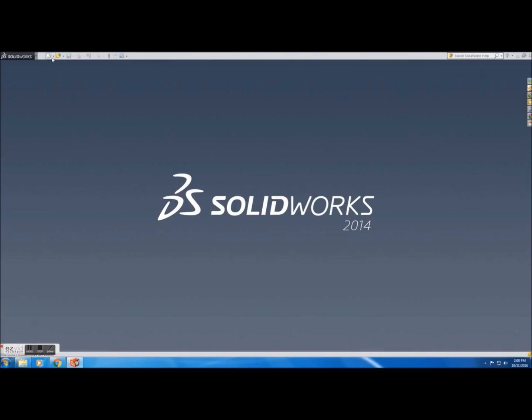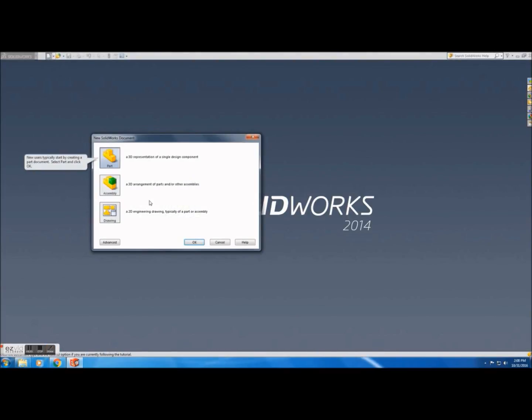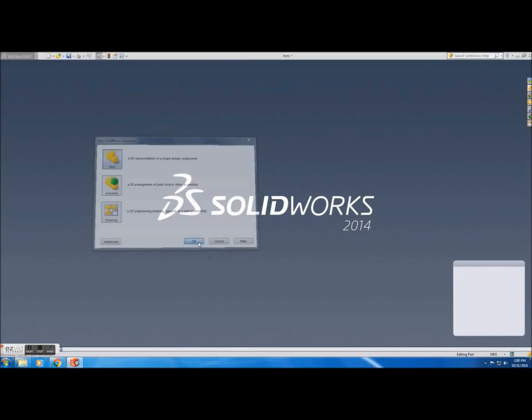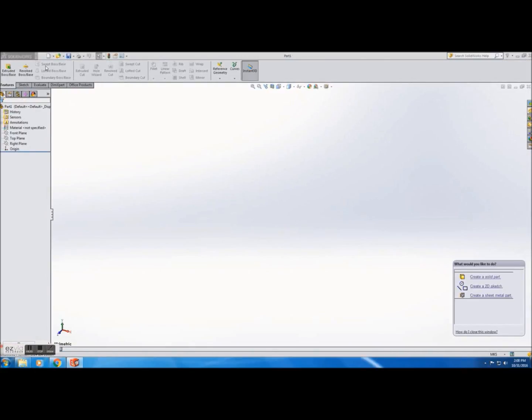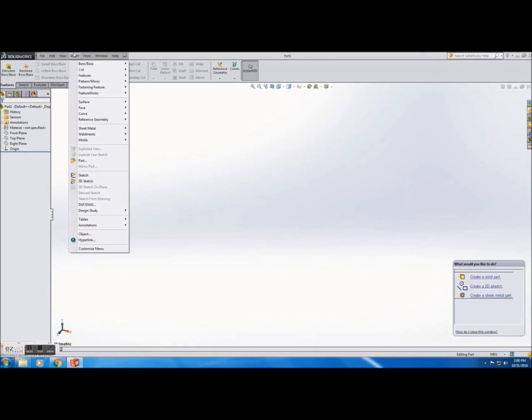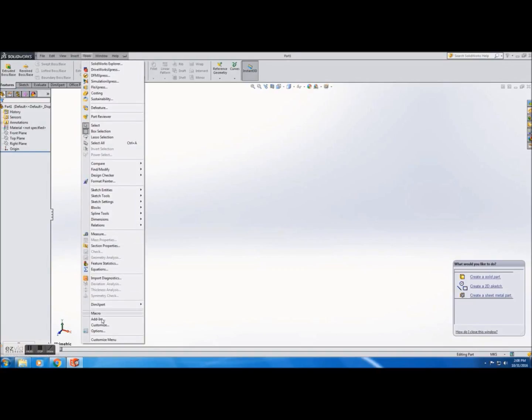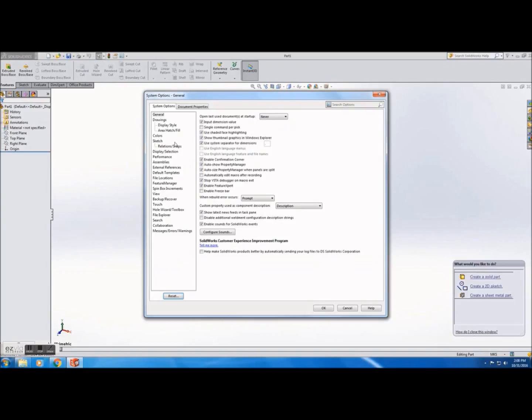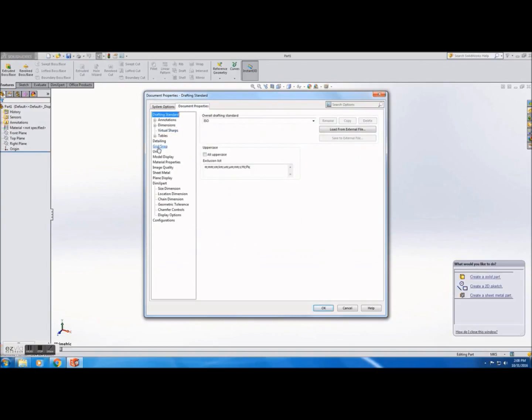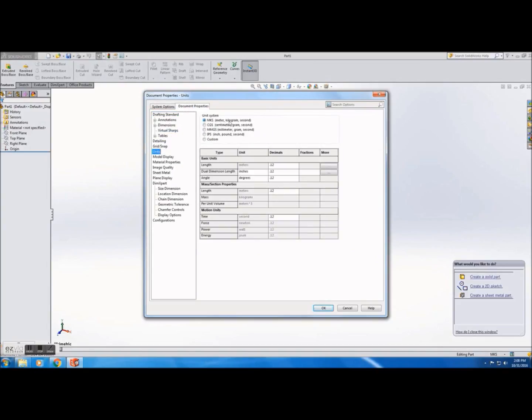Anyway, so we're going to jump over into SolidWorks, set up our document, get ready to actually start importing some of this material and start building the aircraft. You just want to make sure that we're working in the meters, kilograms, seconds units here rather than anything else, because if you find yourself working in millimeters and whatever, you guys have probably done the SolidWorks basics already, so no need for me to explain that to you.